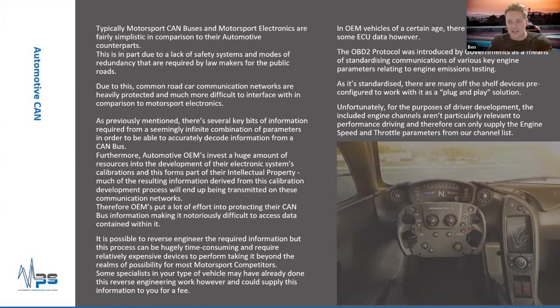The CAN buses in road cars are hugely safety critical in many applications. So they are protected very, very well. There's lots of safety systems in there. You imagine you don't want to accidentally send a 100 when you're meant to be requesting a 10, for example, if you're going from the driver's throttle pedal. I mean, that's an extreme case, but that's as serious as it could get.